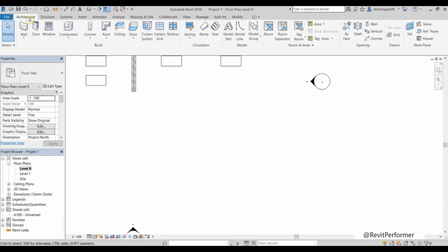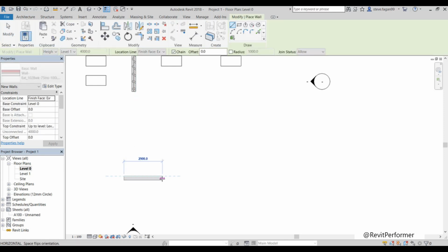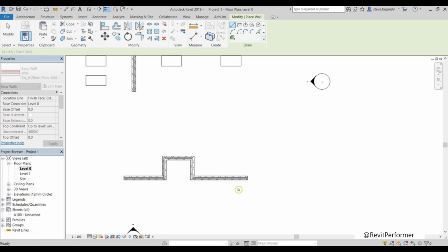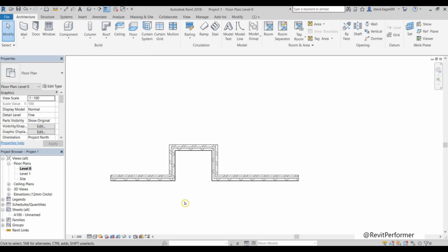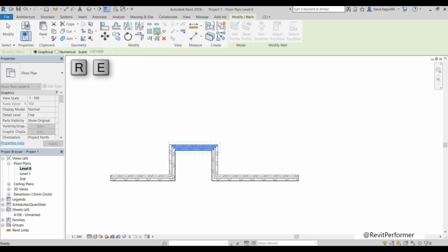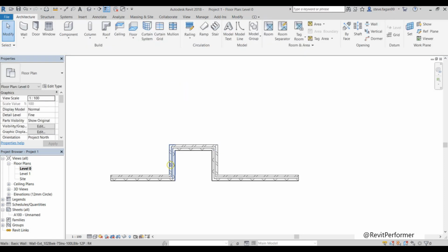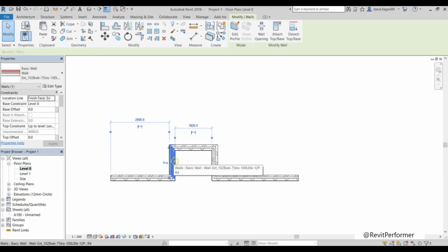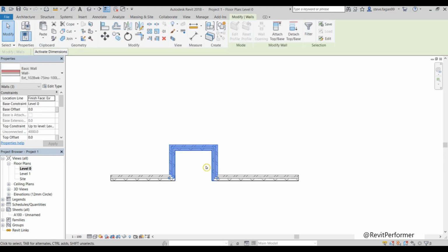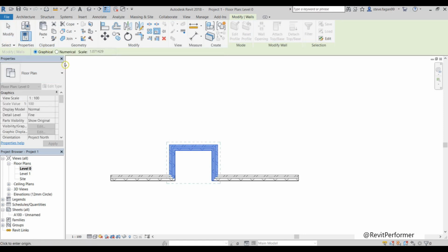So next for the scale, what I'm going to do is just quickly draw a wall. And we have two different types of scale. When I select my element and select scale, we have graphical and numerical. First I want to show you the graphical scale. I'm going to first select each of the 3 walls. I do this by clicking on one wall, holding down Control and selecting all 3. Then I'll select scale, remaining on graphical.